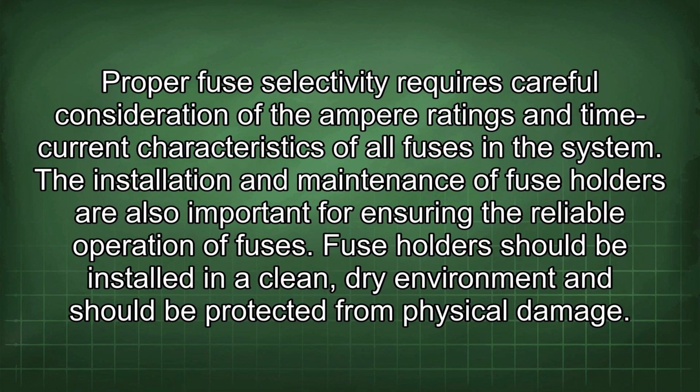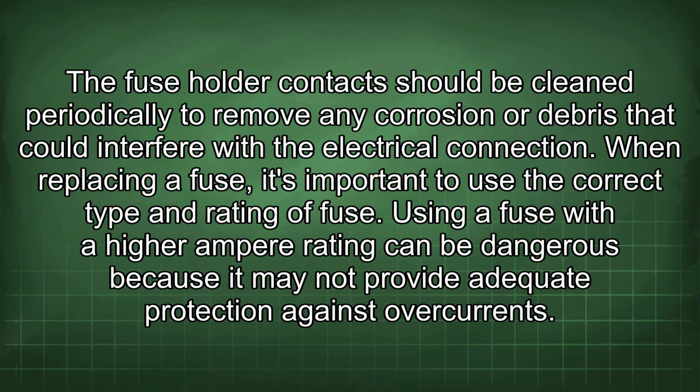The installation and maintenance of fuse holders are also important for ensuring the reliable operation of fuses. Fuse holders should be installed in a clean, dry environment and should be protected from physical damage. The fuse holder contacts should be cleaned periodically to remove any corrosion or debris that could interfere with the electrical connection. When replacing a fuse, it's important to use the correct type and rating of fuse.